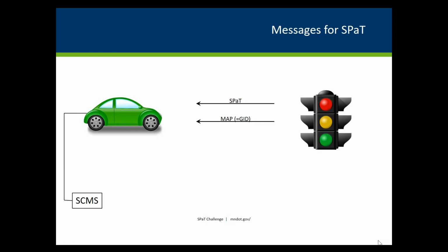Because at the same time, the SPAT message is saying it's green for one direction, hopefully it's saying it's red for conflicting directions, right? So the car has to be able to know which piece of that applies to me. That information you can get either by surveying the intersection, or maybe you got GPS as built when you built the intersection.